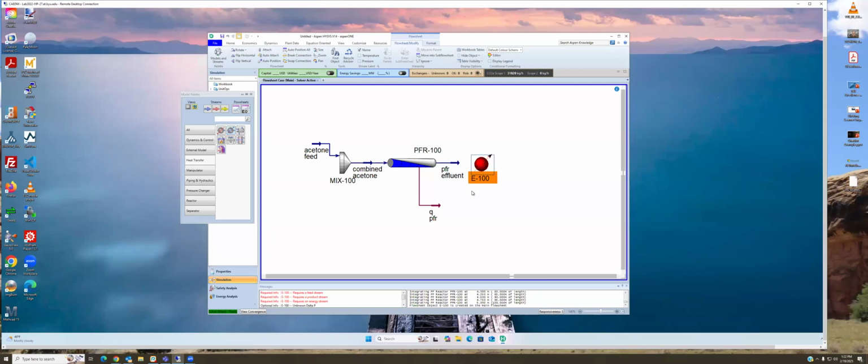And then remember, we said that if we feed sufficient amounts of acid to the second reactor, we can assume that all the ketene is reacted away. And we said a 2-to-1 ratio would accomplish that. So we need to make sure that we feed at least that much acid. Okay.